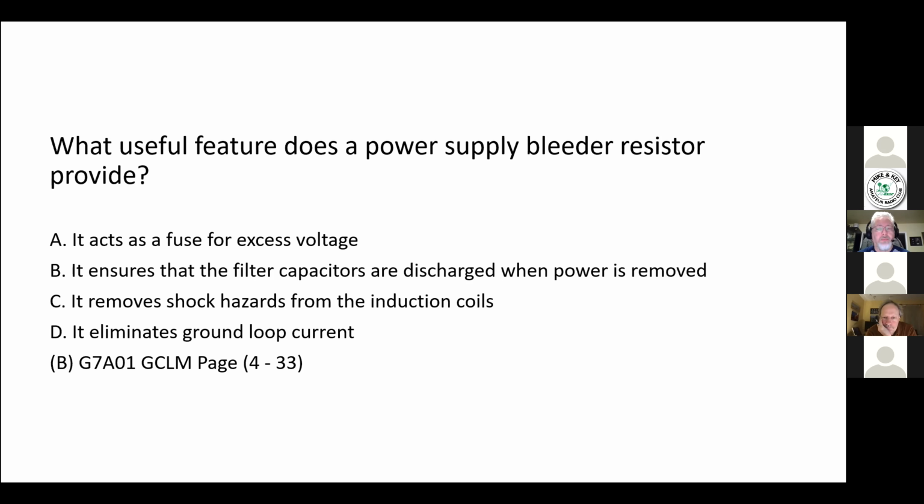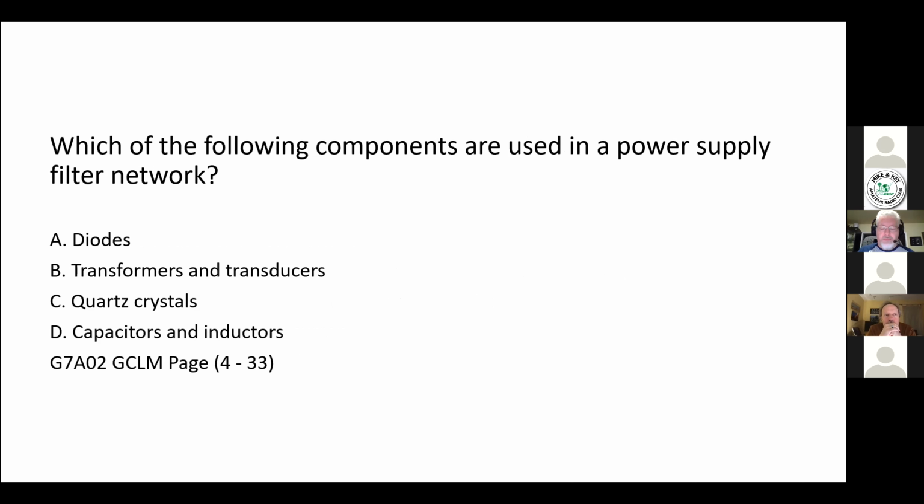So you can disconnect the power, open the case, walk away, go get a couple cups of coffee, then come back and work on it. They mentioned in the videos you should allow up to an hour on some because of the capacitors in some of them. There's a question in the extra class that's 7.5 minutes times 5, so it gives you almost 40 minutes, 37.5 minutes to let it discharge down. Wow.